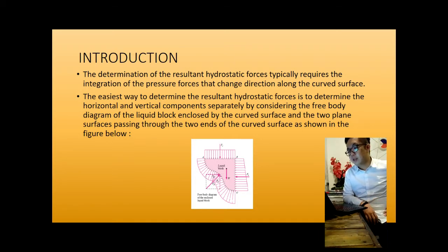In practical applications, such as a large water dam, the retaining structure surface may be curved and submerged under the water. The determination of the resultant hydrostatic force typically requires the integration of the pressure forces along the curved surface.